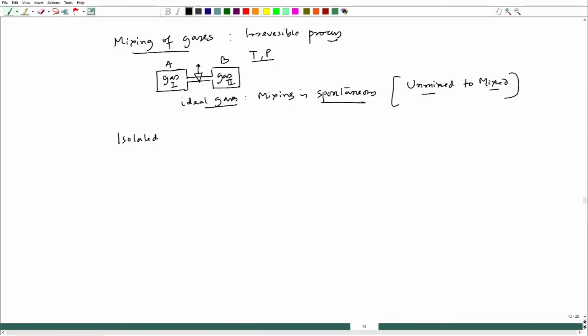And another interesting fact is, let us say I consider an isolated system. So, what is an isolated system? Del q equal to 0, and we know that del u equal to minus del w, because it is surrounded by an adiabatic boundary. That means the system possesses some internal energy and does some useful work by spending its own internal energy.